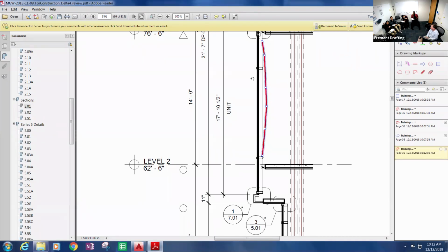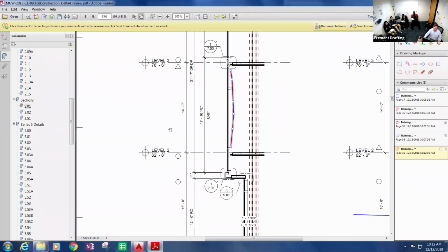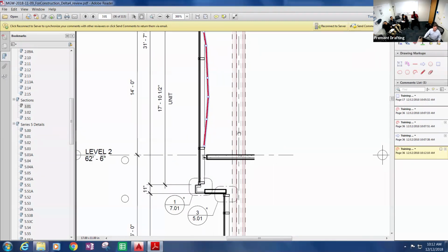So you're really looking at two things. You're looking at the vertical mullion itself, anchor to anchor. Yep. So that's the aluminum. Correct. Then you're also looking at the glass. Correct. If it's a big span. Yeah, right. So then when you say 3/4 max, is it 3/4 from the face? Like where do you measure it from for the glass? Is it from the face in the middle, the worst point? Or like you said, just the tips?